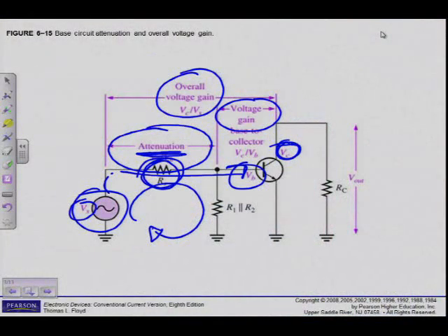He says then, the attenuation is 2, which can be expressed as a gain of 0.5 because gain is the reciprocal of attenuation. But for me that was superfluous. I would have said 0.5 right from the beginning because attenuation is 0.5. So you can approach it that way as well, or you can approach it the way that the book is using it. He says, suppose a source voltage of 10 millivolts input signal and a source resistance combined with the load resistance results in a 2 millivolt output signal. In this case, the attenuation is 10 millivolts divided by 2 millivolts, which is 5. That is, the input signal is reduced by a factor of 5. This can be expressed in terms of gain as 1 over 5, which is 0.2.